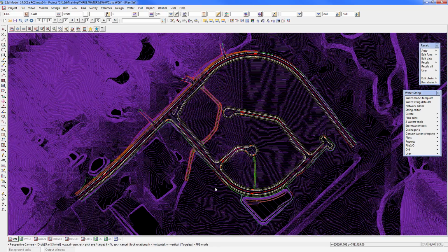And by the time you've located all the crests and sags and these other critical locations, a lot of the locations of other pits will then naturally fall into place because they'll be dependent on these critical ones first. So get the critical ones out of the way and locate them, and the rest then become a little bit easier. You're not starting from scratch, in other words.